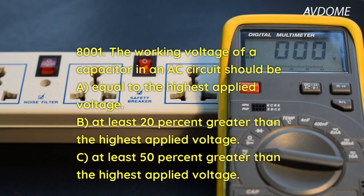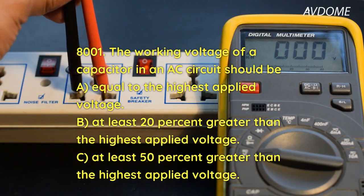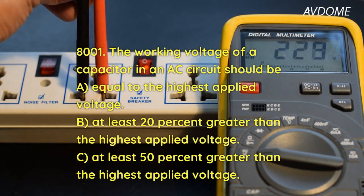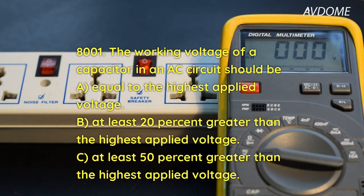8001. The working voltage of a capacitor in an AC circuit should be A, equal to the highest applied voltage, B, at least 20% greater than the highest applied voltage, C, at least 50% greater than the highest applied voltage.